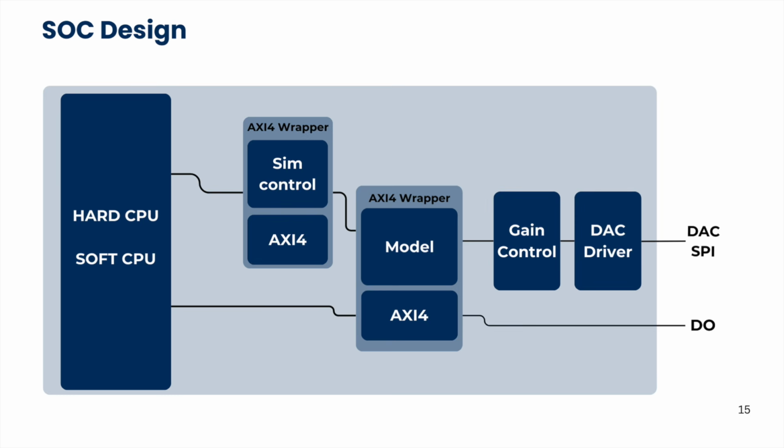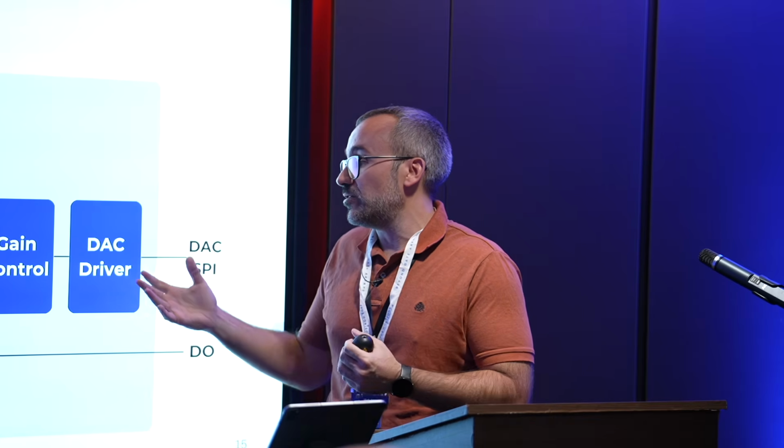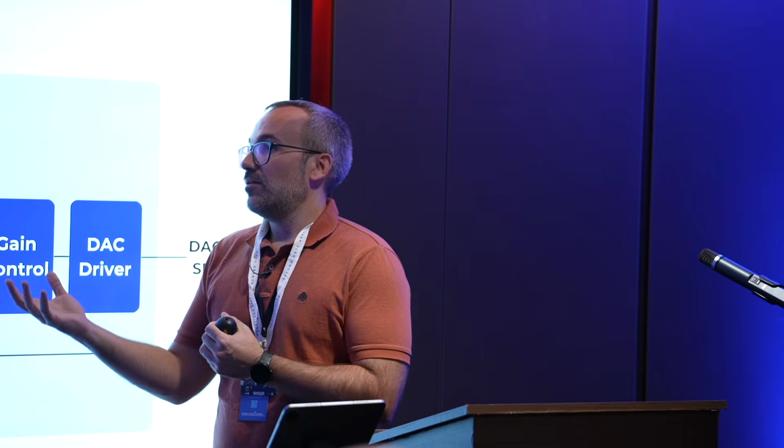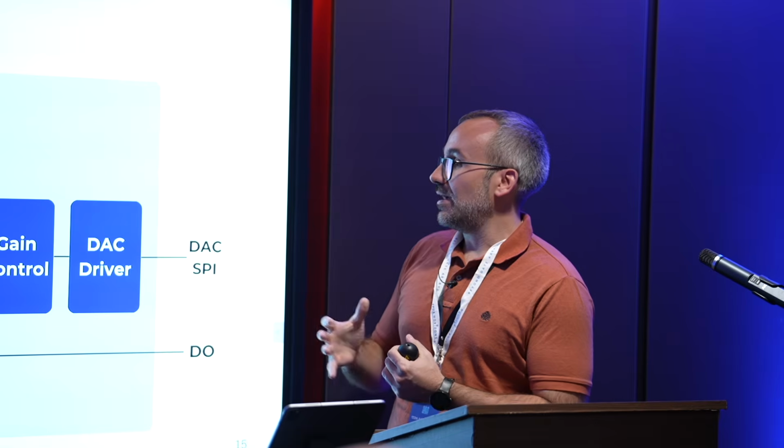If we are using an SoC, like a Zynq or a PolarFire SoC, we can replace some of these blocks. For example, we will have a hard CPU or a soft CPU, and then both the simulation control and the model will be managed by an AXI wrapper. The gain control and the DAC will remain, because we still need to extract the measurements to our control platform.